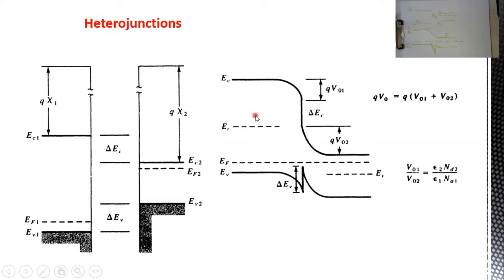Here, the plotting is more consistent and to scale so that you can see it in a better way. This spike is actually a very recognizable spike in the semiconductor field. And it is the main reason to have what's called an internal boundary or interlayer capacitance. Usually, we agree that a normal p-n junction has a capacitance due to the depletion region, but this is another source of internal capacitance.